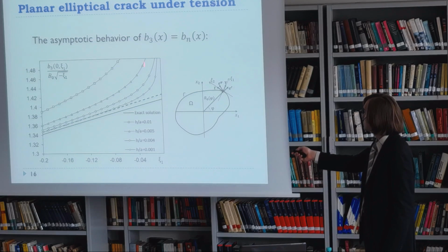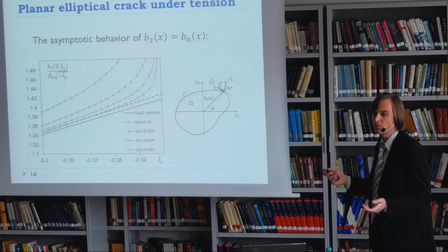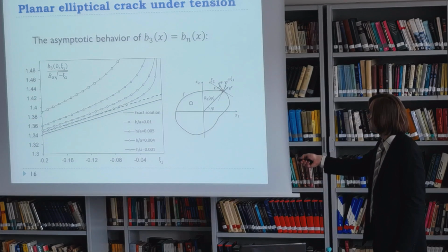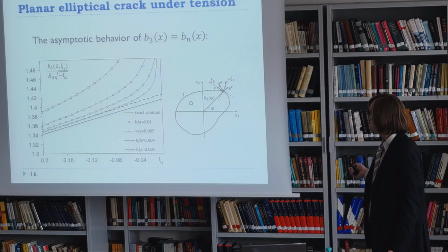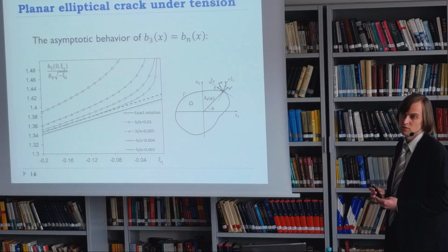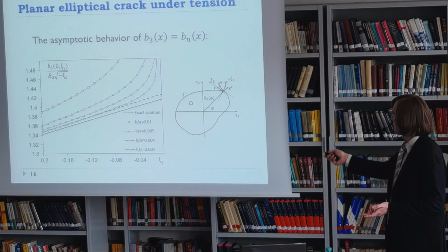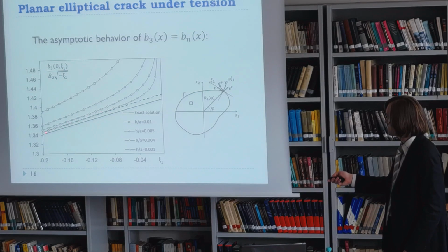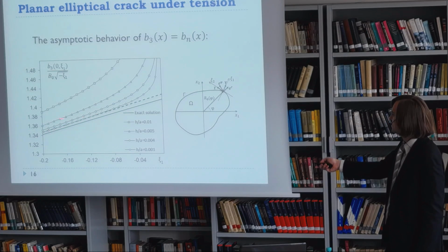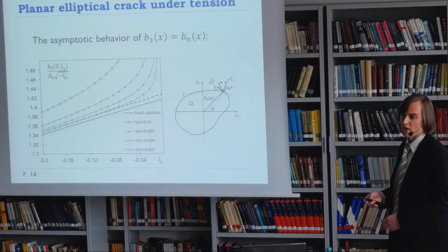But of course, because the crack opening is not zero at the crack edge, it rockets to infinity. So the most obvious solution here would be to discard this value, which we cannot consider for the solution, and just take this value of confidence and extrapolate it to the crack edge.